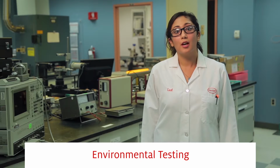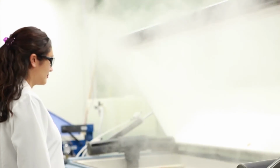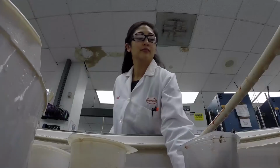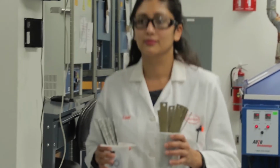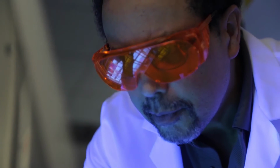In the real world, bonded parts are exposed to various temperatures, moisture levels, and harsh chemicals, and we do the same to our assembled bonds in the laboratory. Longevity studies and endurance tests are crucial for determining adhesive choice and product shelf life. Packaged adhesives, bonded or cured parts are placed in environmental chambers or immersed in chemical solutions for a specified time period, after which their performance is evaluated.